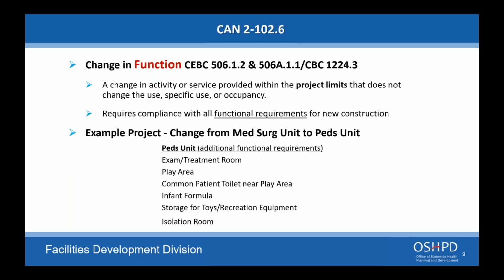Again, there is a requirement to balance the air that you're serving. Now, again, it's going to depend a lot on the area being served, what functions in there. You know, if it's an OR, it's going to be a way different requirement than if it's administrative. There are actually some clarifying statements there in the narrative in the code for when it would apply to rebalance. But you need to expect there's a certain level of rebalancing when you put in a new unit.